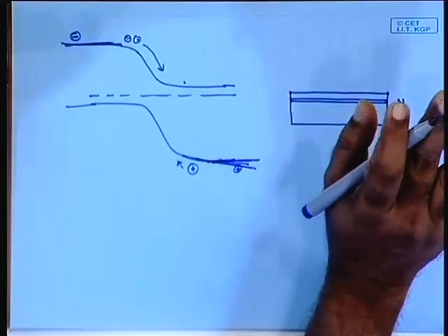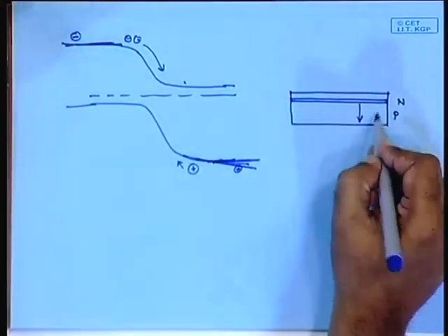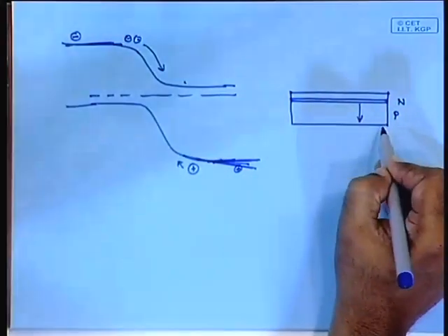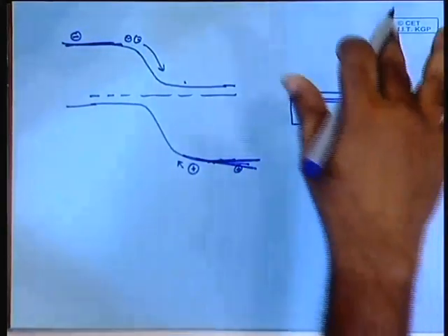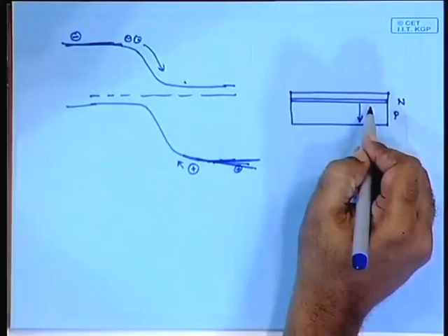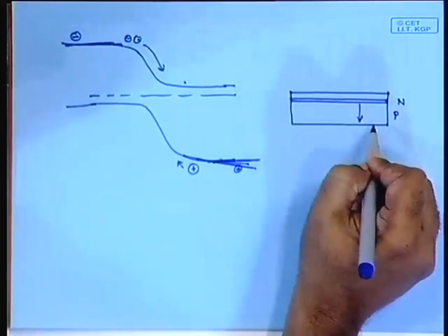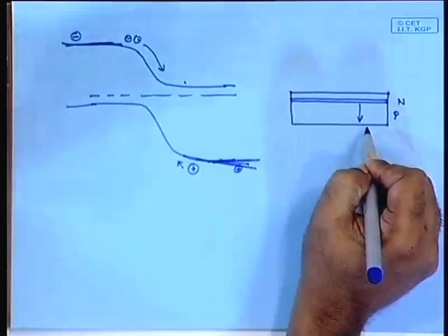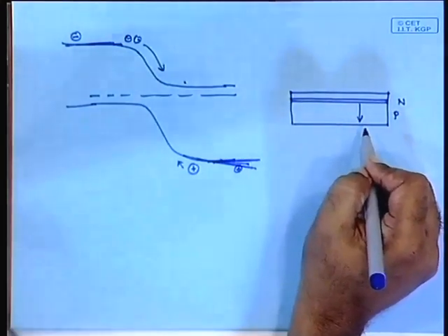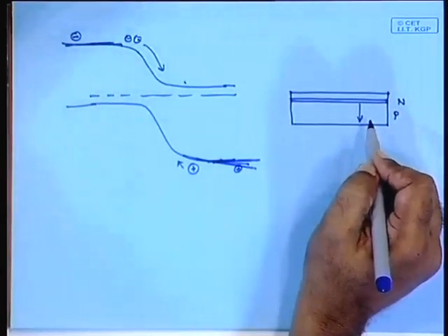Now, this is very common nowadays, but if you produce the whole P layer as just one and then grow on top of it the N layer, obviously you cannot do that. So, there has to be some additional doping put at the bottom level of it. There are technologies for doing that in silicon as well as in these materials.